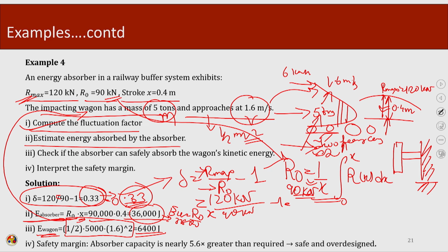Now check if the absorber can safely absorb the wagon's kinetic energy. So, we need to compare the wagon's kinetic energy versus the energy absorbed by the absorber.